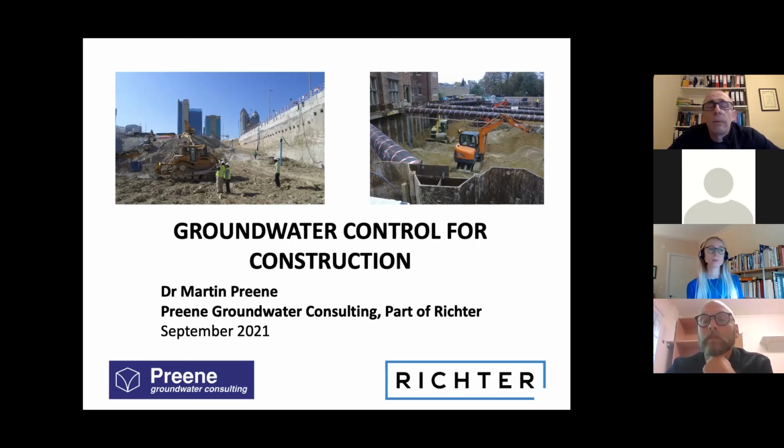And also, particularly now, increasingly, when people are building new metro systems or new road systems, they need to at some point connect into other tunnels, existing tunnels, and it can be quite awkward to do ground treatment or dewatering where you're connecting your new tunnel to an old tunnel or an old shaft. And I get the feeling that ground freezing is often used for small pieces of work where you're connecting in. So yeah, it's a method that's used rarely.